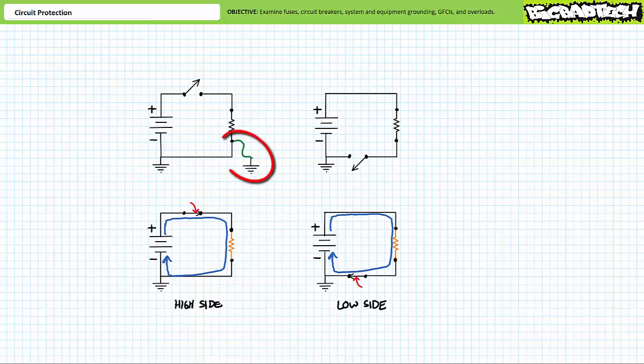In the high-side switched arrangement, an accidental connection of the load to ground does not energize the load because the load is already at ground potential due to the system ground connection and open switch. Not so in the low-side switched arrangement. The electrical load is always connected to the source and only necessitates a connection to ground to run. Any errant connection to ground can energize the electrical load even if the low-side switch is open. Be extremely careful when working around low-side switched elements.